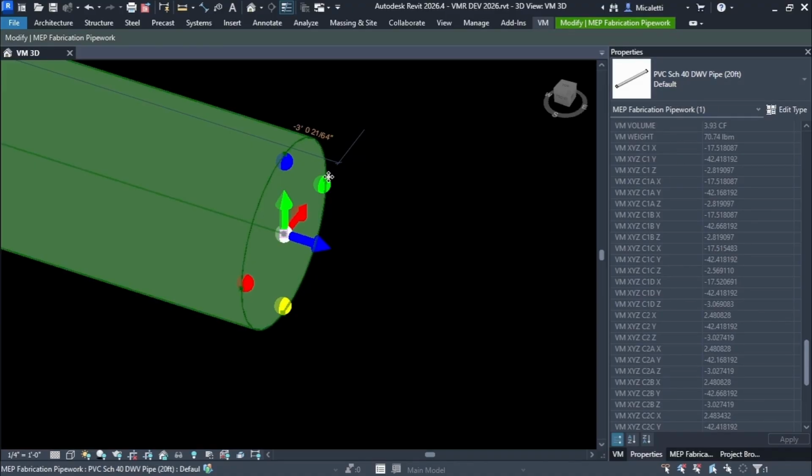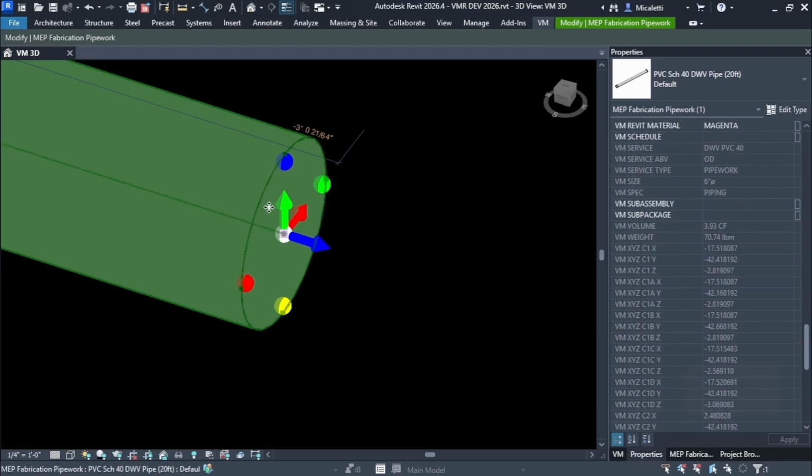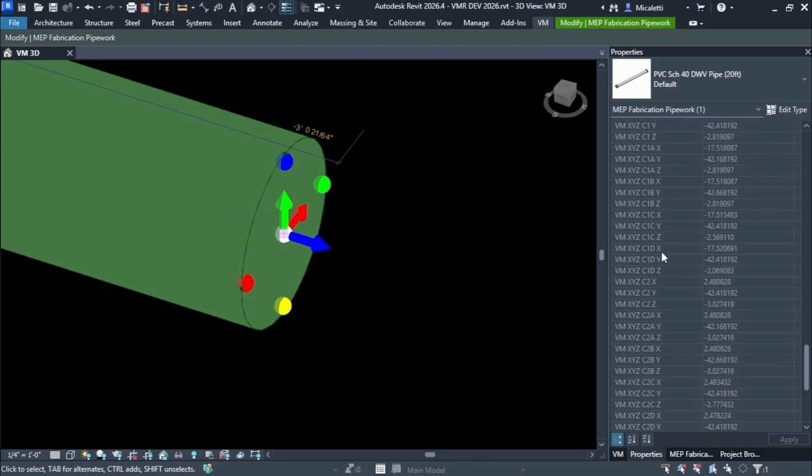So you just put this in a schedule, right? And all the power of a Revit schedule is with you. And not only that, you're not scheduling the points, you're scheduling the pipe. So you can schedule everything about this pipe along with the points. Right, so that's very powerful. Is there any specific feature you're looking for with quote unquote management?